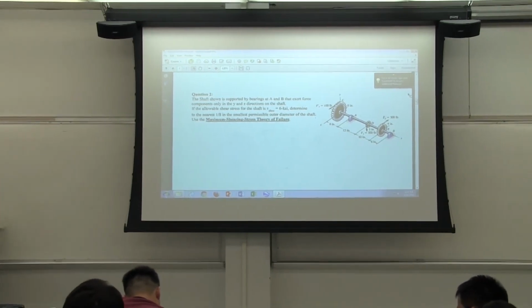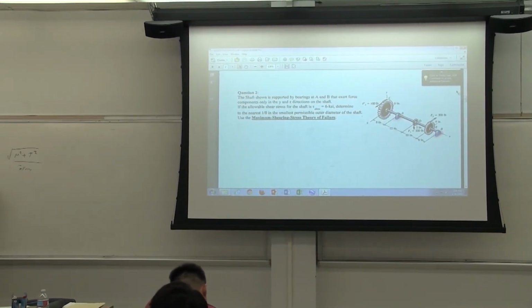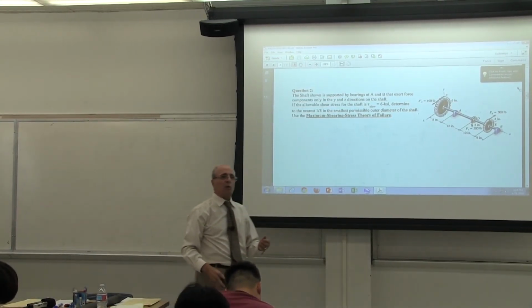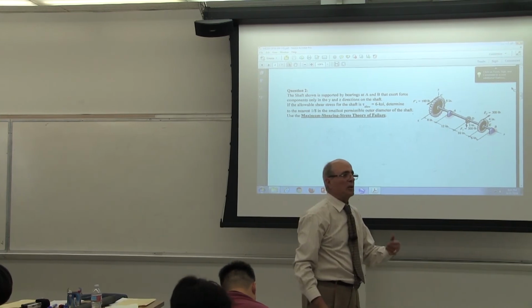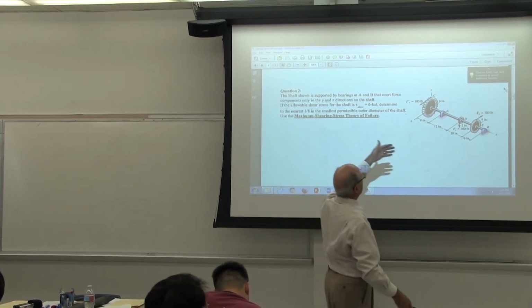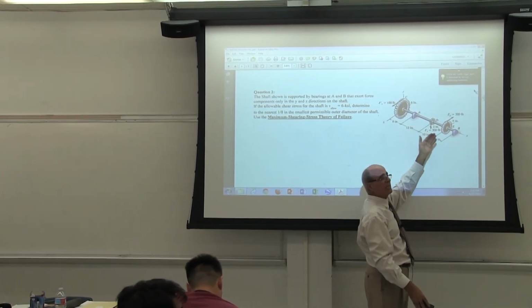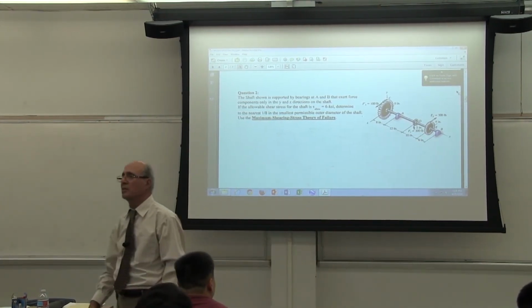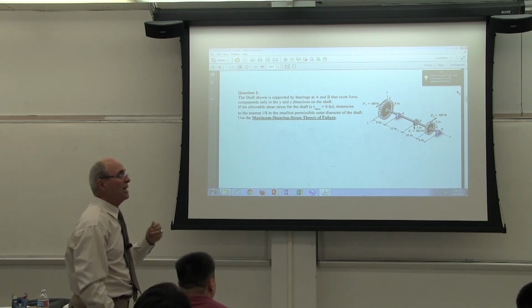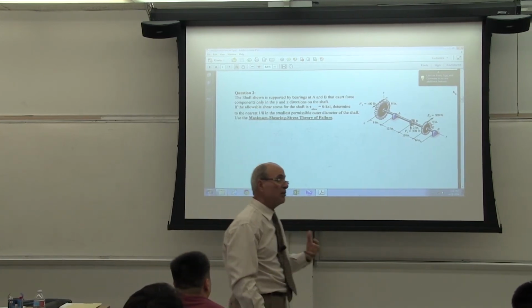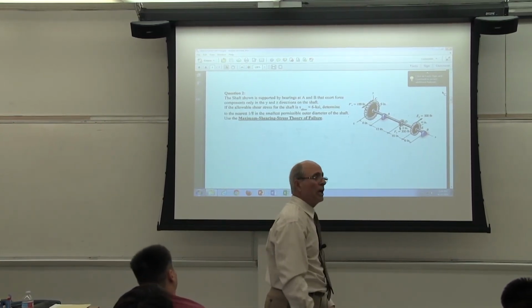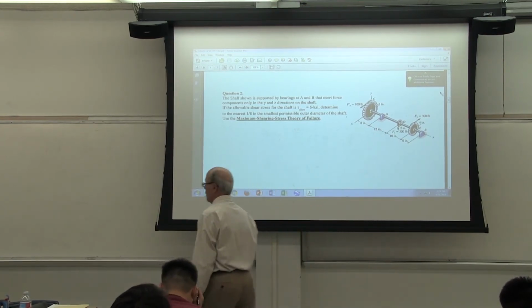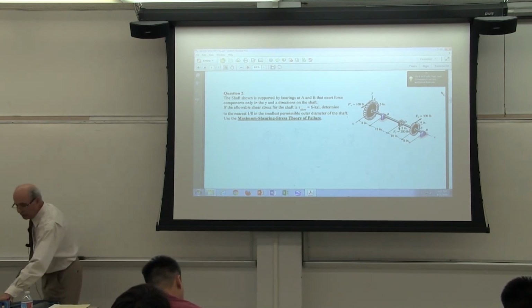Remember in the analysis, I said we need the maximum torque, maximum M. Didn't I say that? The maximum depends. It may happen at A, may happen at D, may happen at E. What is the maximum at that point? Is that correct? That's the whole issue here. So by saying maximum torque is 1200, you are giving me the right answer, but that's not going to help me. I need to draw it. Is that correct or not? Everybody see that?